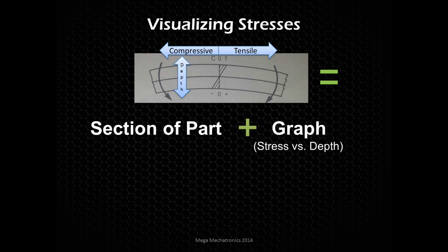If we analyze this graph, what you're looking at on the top side is a tensile stress. Since that line is on an angle, crosshatched, you can see the maximum tensile stress this part is seeing happens to be at the very surface of the part. Then we move into the middle, and you see there are no stresses there. You can almost think of that as the pivot point. This is a very symmetrical example as well, but we're just trying to get the idea across.